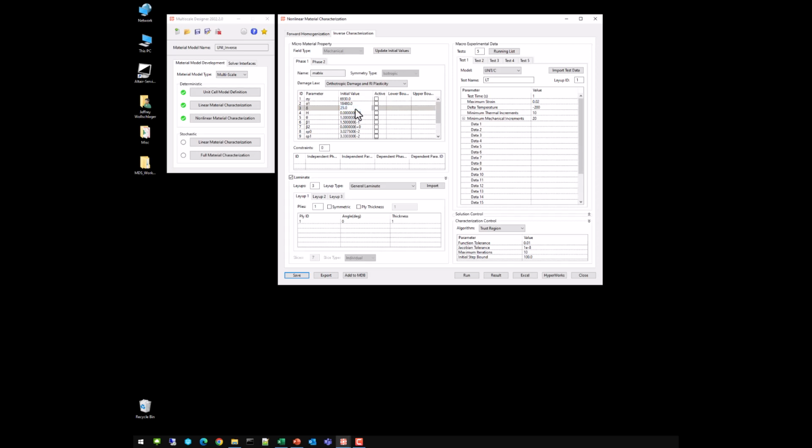For these kinds of specimens, it's anywhere between 0 and 500, but these specimens are going to be somewhere around 100 or below. But we'll start at 25. It's going to be an active parameter. And my hardening slope, H, is going to be 10,320 psi. All the other values are fine as they are. I'll just type them explicitly.